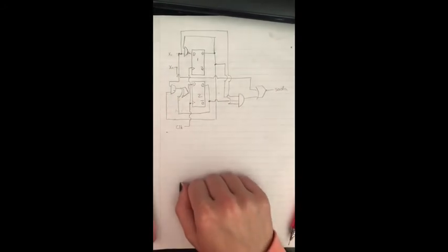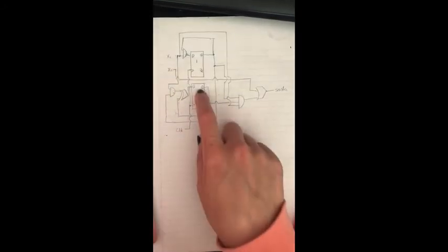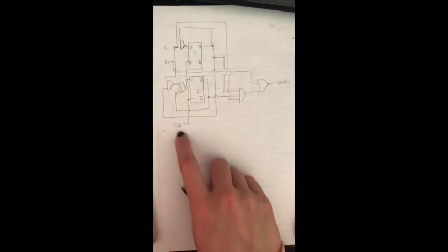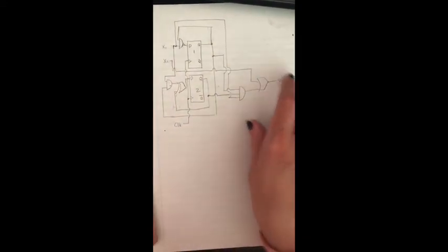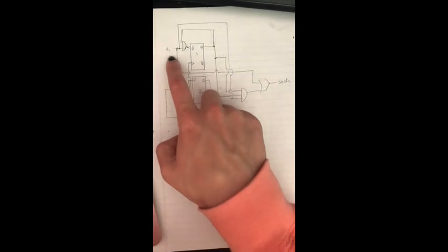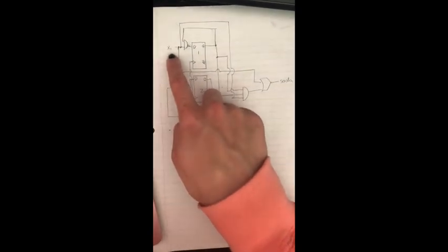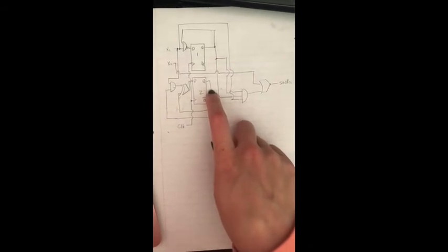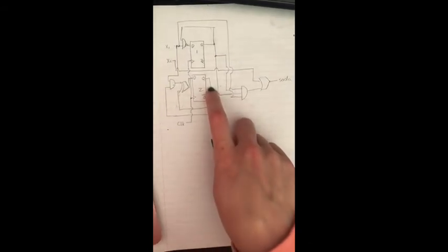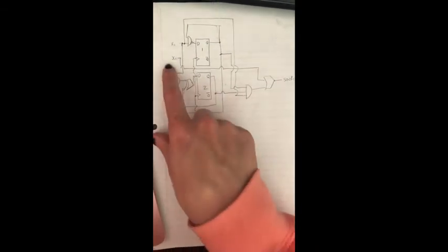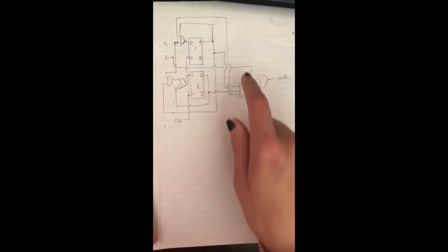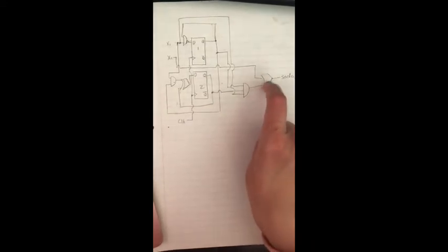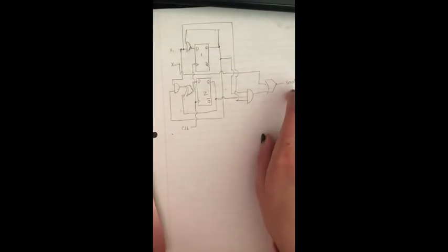So here we have the circuit diagram, which consists of 2 D flip-flops, 2 bits of input, one for the quarter, one for the dollar, a single clock bit, and an output representing soda. The X1 quarter input bit will feed into the 2 D flip-flops to cause the various state changes as we input more quarters until we get a soda. The X2 dollar input will bypass all of that because it does not actually affect the intermediate states and simply gets us directly to the output and the reset to the A state.